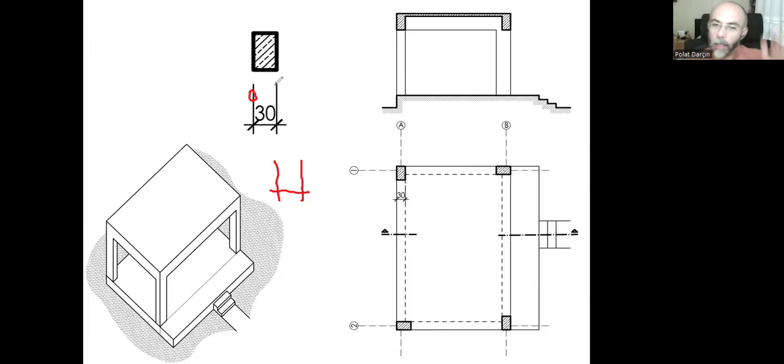And these are like the arms. They are pointing towards the column. So they are giving me this size of the column. And I need to do that 45-degree angle in order to emphasize the size. And I will put my number here, 30. It's in centimeters, but I don't write cm at the end. Okay, just the 30 will be enough. And that's the size of this column here.